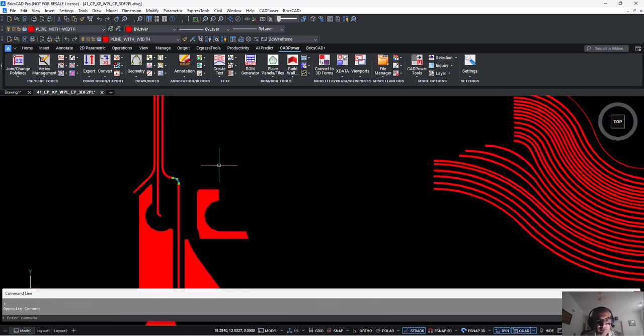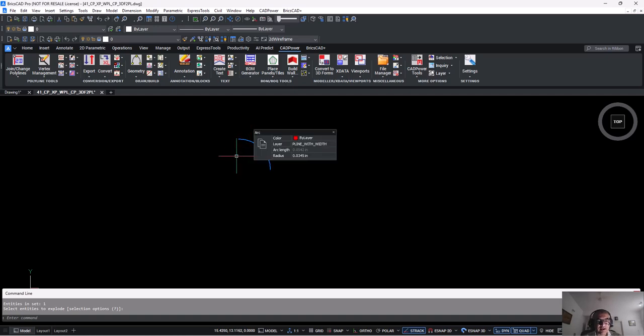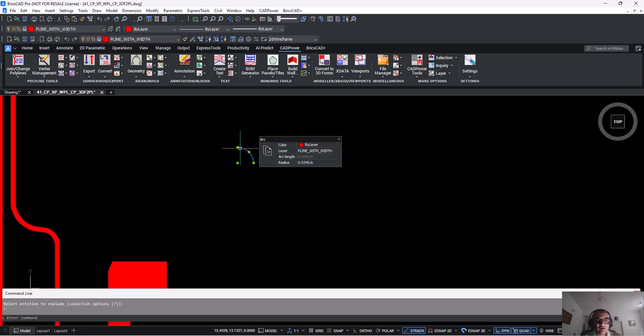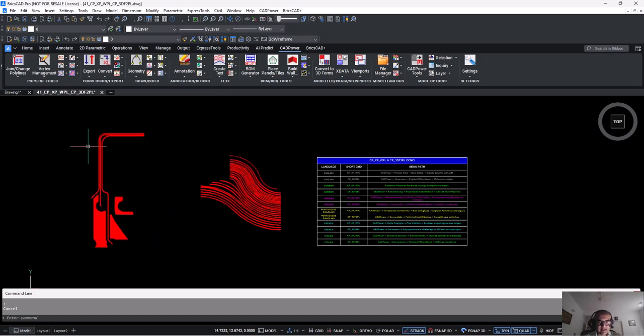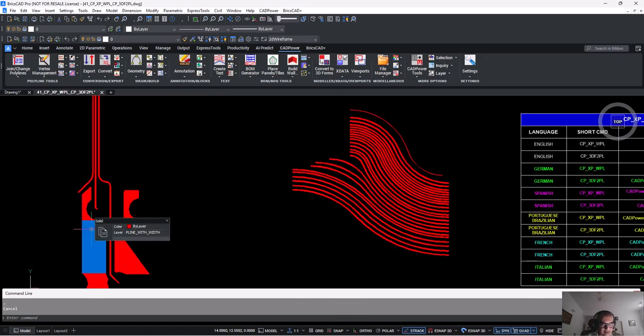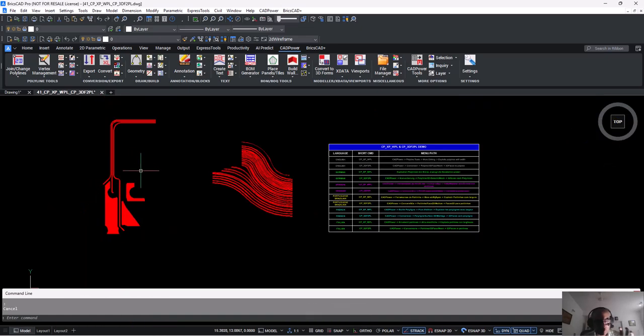For example, I'm going to make a copy of this here and explode it. You can see that the width information is lost and I get just a line or an arc with the width completely gone. Now this is my test case here. There are several solid objects which are solid fills, and several two vertex polylines which have width, and the brief is to capture the exact width information and its geometry.